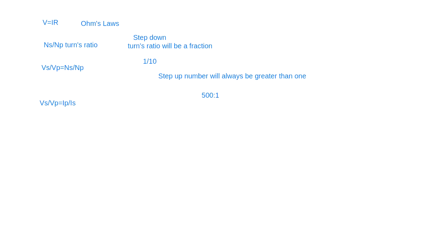When you move to full wave equipment, what happened was they were able to take that negative half cycle, and instead of just suppressing it, they were able to take it and flip it to the positive side. And when they flipped it to the positive side, you still had that 100% voltage ripple, because you still, let's see if I can do this for you. Draw a line. It's hard to draw with your mouse, I'm just going to say that. And you had your single phase half wave.